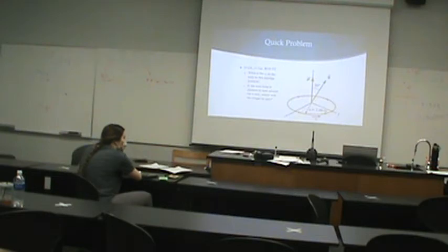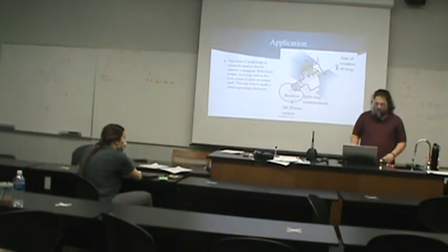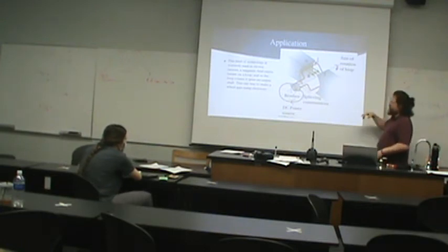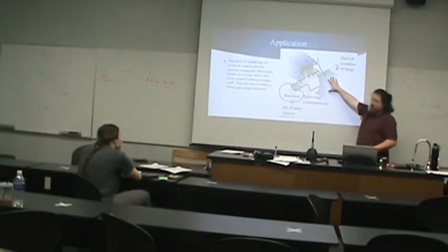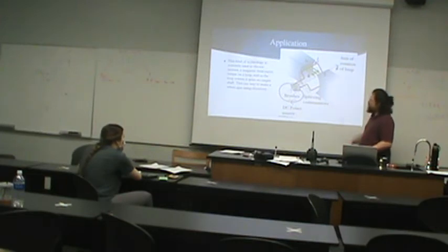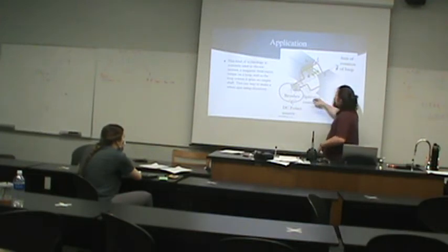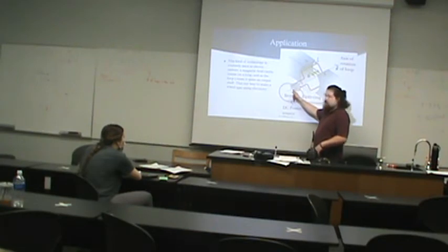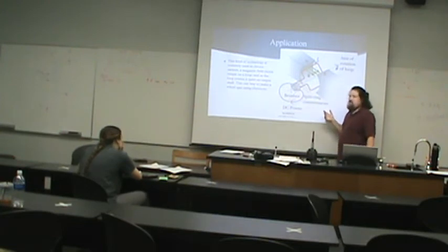Well, what the motor actually looks like on the inside is something like this. We have a loop spinning around inside of a magnetic field. The magnetic field is provided by this bar magnet with a hole in it, basically. And the wire loop is connected to a power source that usually has some sort of a split in it. And when the loop passes over that split, the power shuts off. The circuit is broken.